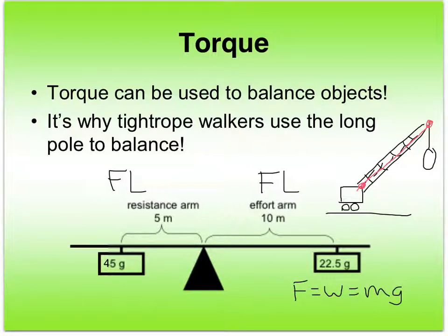So what they do is they place this movable object on the back of the crane that can move back and forth. It's called a counterweight. And this counterweight can increase the torque on the other side, thus creating a pivot point on the crane right here. So this lever arm with this weight is equal to this lever arm with its weight, the counterweight, to help balance this thing so the whole crane doesn't topple over.